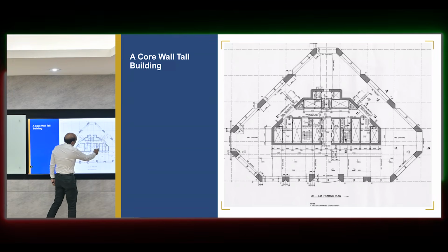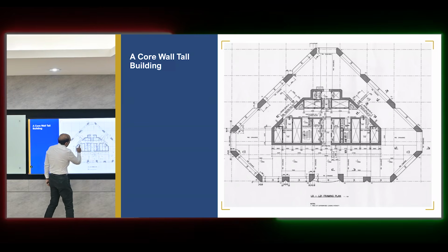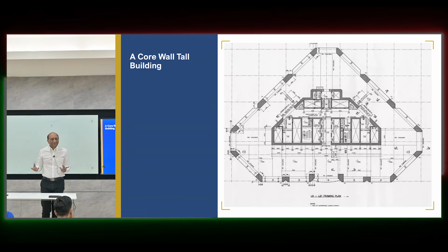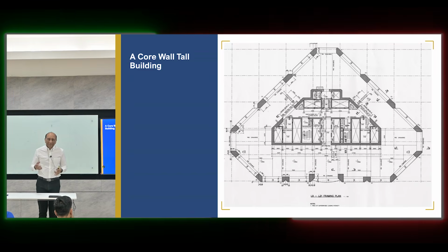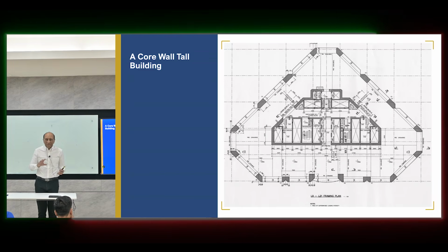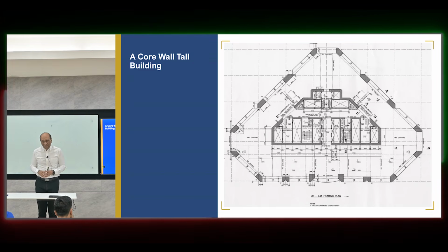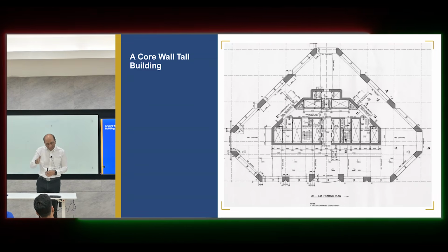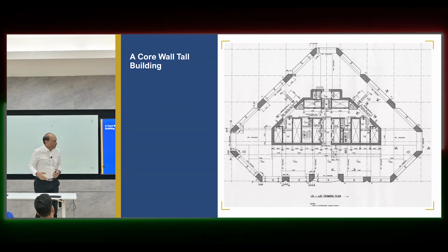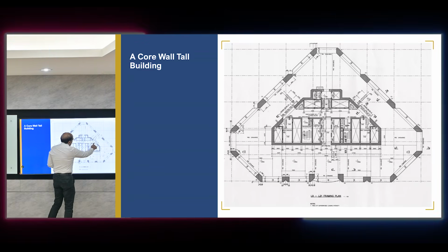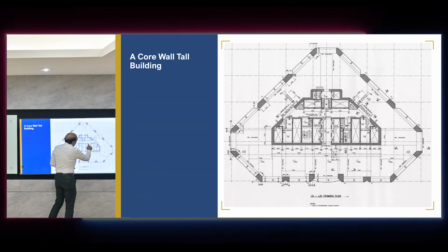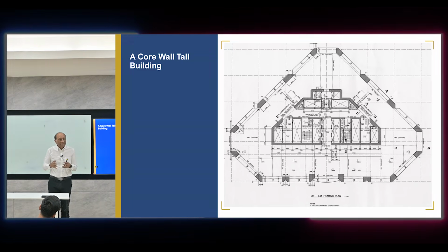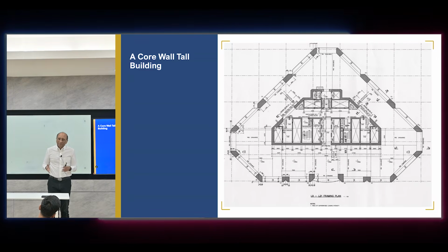Inside are thin walls. Normally, they cannot be used for structural purposes, because as soon as you put a wall there, it will start attracting shear. And we will learn later that in a shear wall, bending moment and shear are distributed very, very differently. If you remember in the first course, we talked about that if you have a web, it will take the shear, flanges will take the bending. So as soon as you put a wall here, it will start to take all the shear, because that's the main web inside. But the thickness is not large because they don't need the space.